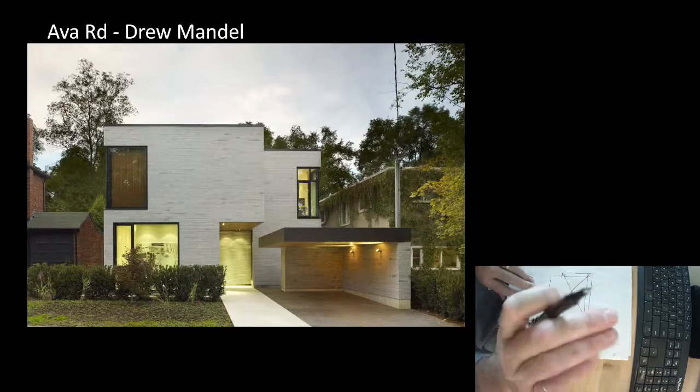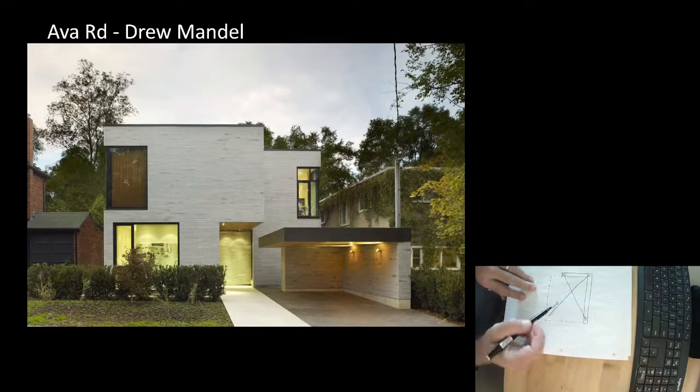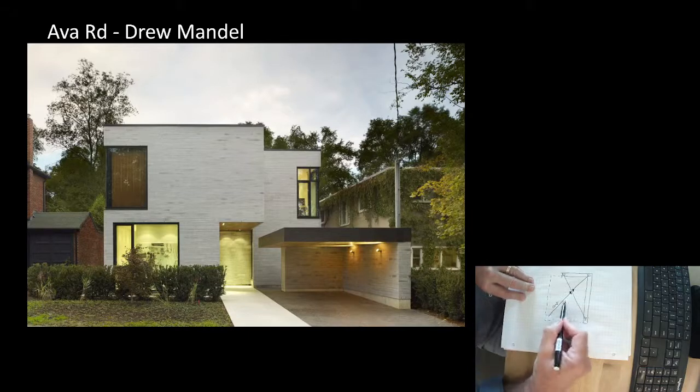But if we want things shallow, we want to keep it shallow so that the whole system isn't too deep. You break that cantilevered beam here and here. This is our symbol for a moment connection. And we put a moment connection so that the moment in this beam transfers straight through that beam. So very elegant, very simple. And then this simply gets infilled with wood joists.